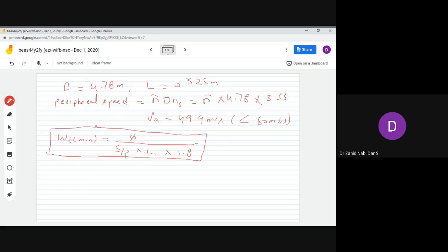Again, you can recalculate the Bav value as p phi divided by pi D L. Because you don't have a phi value, it will be Bav into pi D L divided by p.